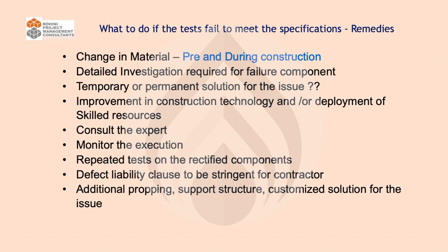Let us say you want to work on an earthen dam. That's a very common sight in the lakes also. You have trees growing on the incline or something, so they have to be transplanted or taken out. If the trees have gone to the core, then obviously it is going to be difficult to remove the trees without touching the core. If you do that, you should ensure the core, which is the center portion of the bund, right? That is where the entire loading is coming onto, and you need to be clear about how it will be protected.